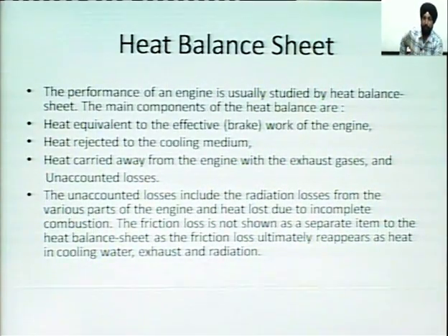So, some amount of heat is carried away by the cooling water, some amount of heat is carried away by the emission or by the exhaust gases, some amount of heat will be lost to the surrounding air by convection and radiation, and a fraction of the heat supplied to the engine will be used to develop the output, which we call brake horsepower.